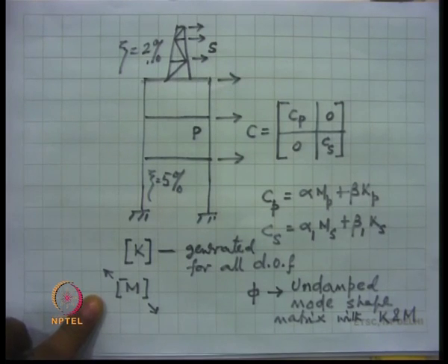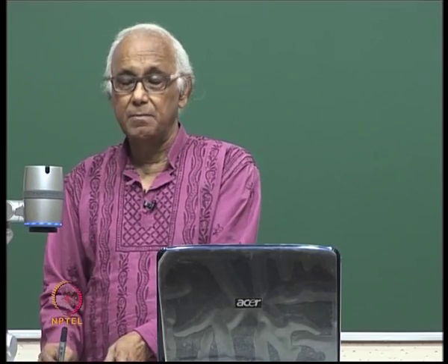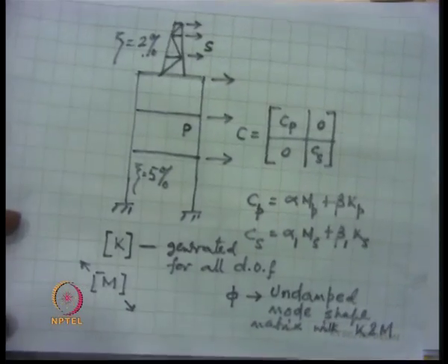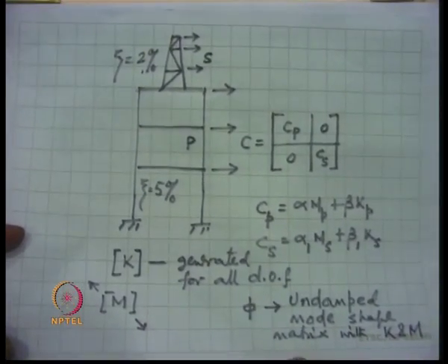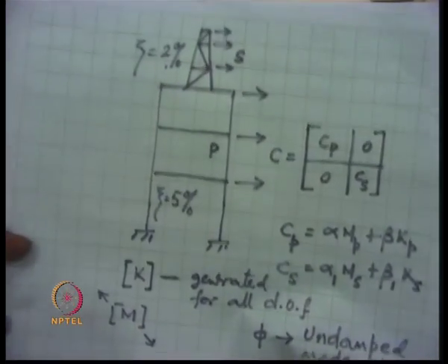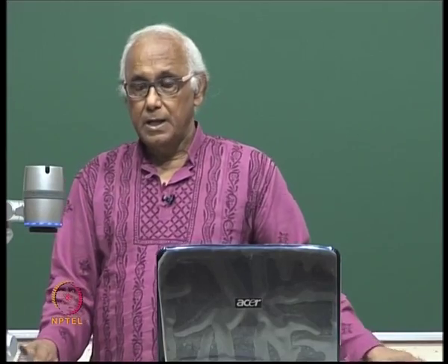Therefore, one can obtain the necessary spectral ordinates for acceleration for a given damping and given time period. Once we get the equivalent set of lateral forces in each mode of vibration, then we can apply them and carry out the usual static analysis performed in the case of response spectrum method of analysis.